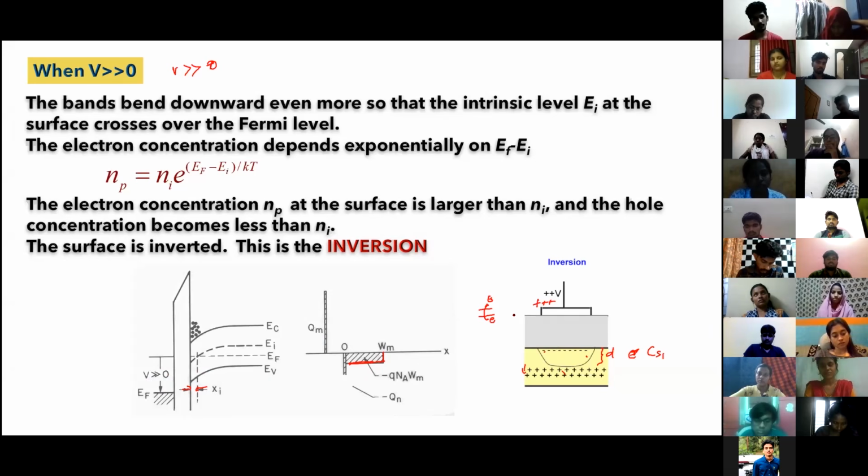Here you have a positive side, and your electric field is very strong because of the high voltage. Once these electron-hole pairs are formed, the electrons go closely to the semiconductor and make a small layer, which is called an inversion layer, and the holes are pushed down further, and more charges will also be there.